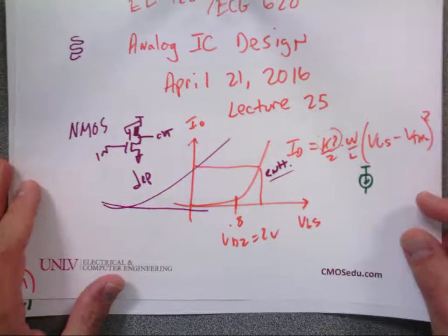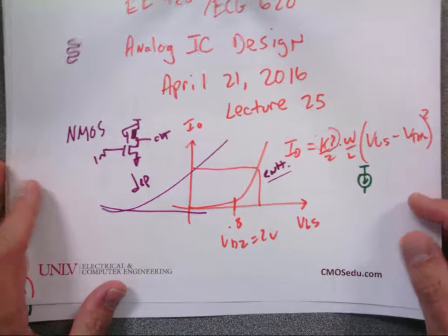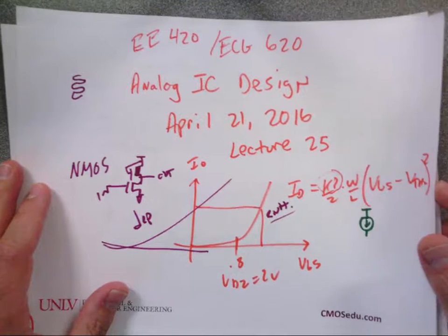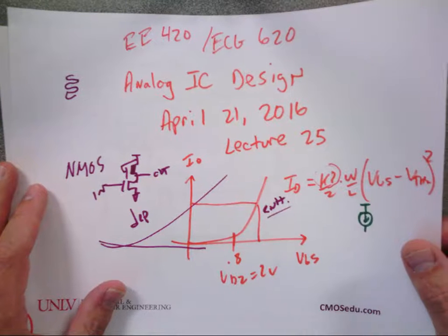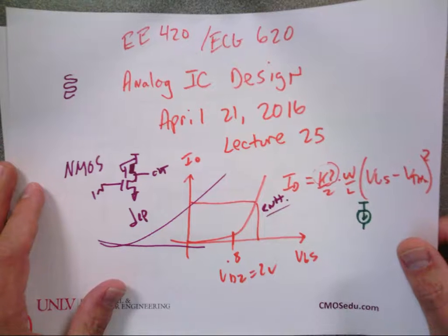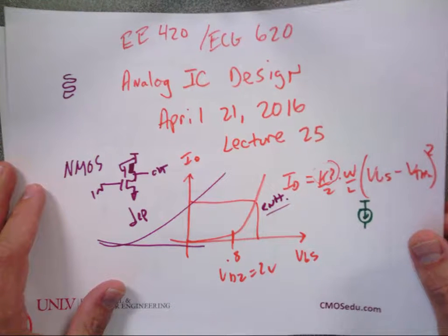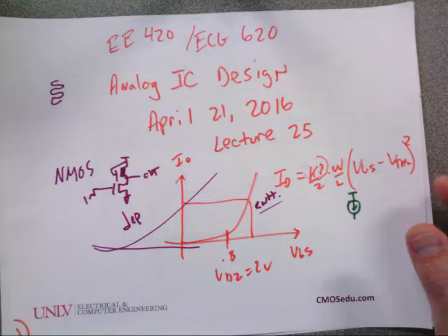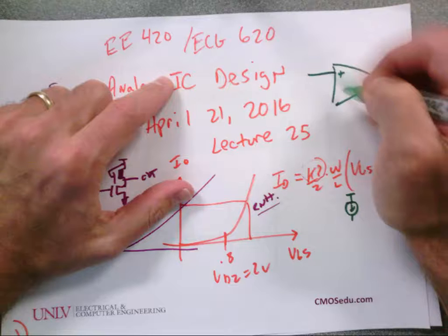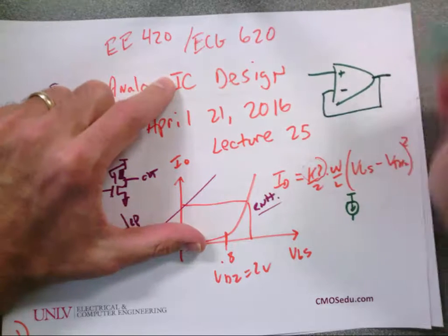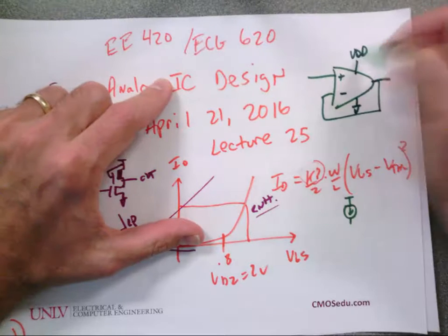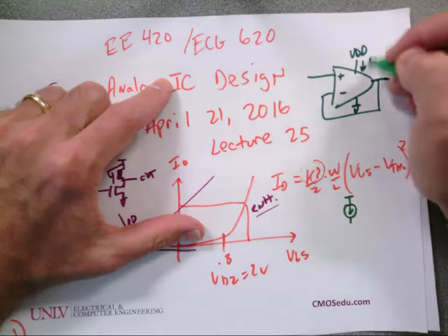Okay, you said specifically VDD, 10 microns, no driving more than 10 milliamps. What's that supposed to mean? That's the power supply current. VDD is your power supply. Here's my op amp. This is the circuit I'm designing, right? Connected to it is a ground and power. The maximum current that I can supply there is 10 milliamps.